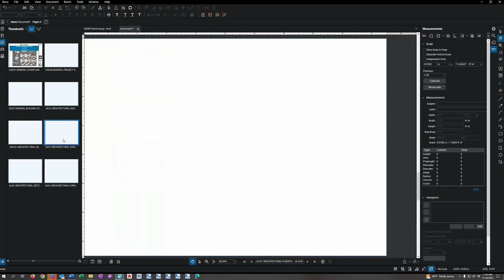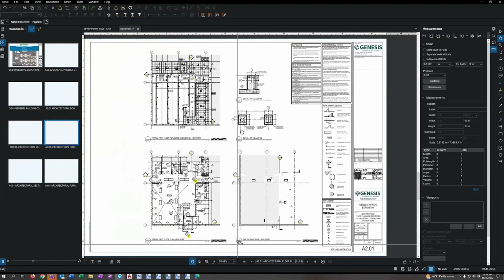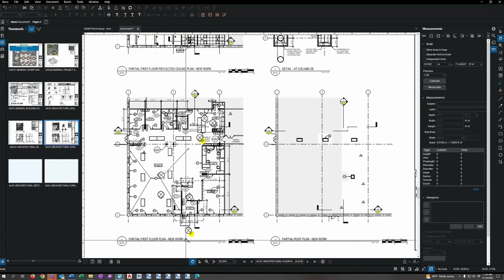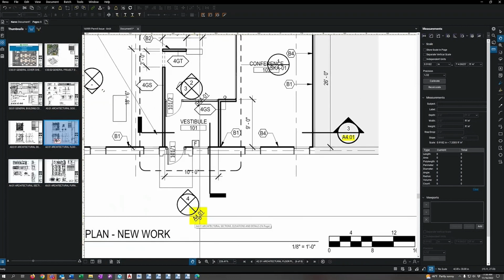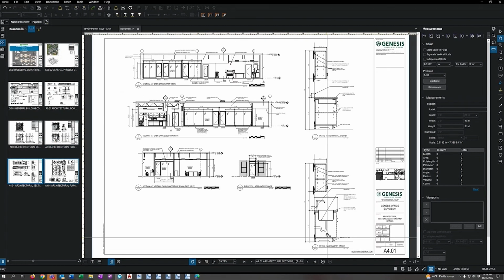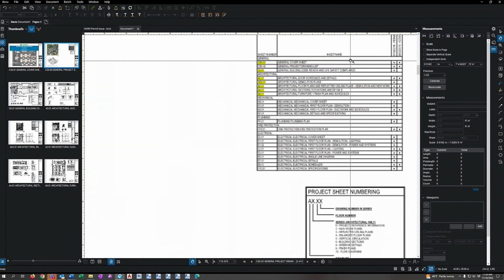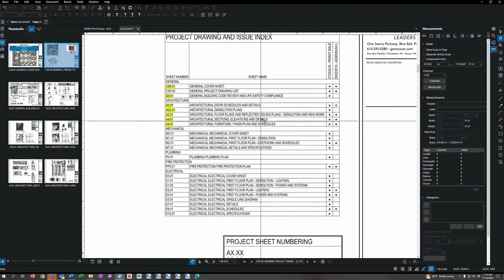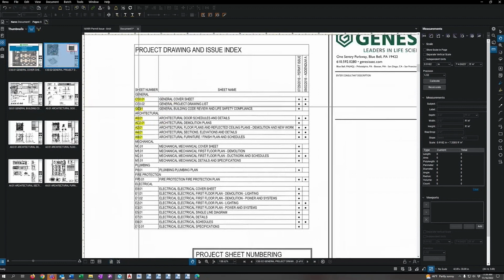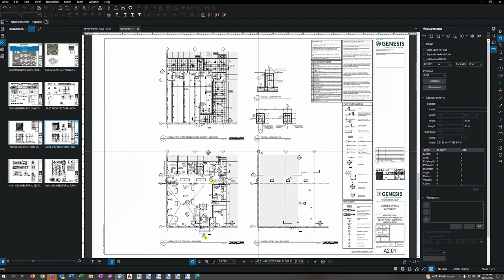if we go to a different page, you can see highlighted in yellow where all the links are. So it found this on the page, and A401 now points to that page, which for us is down here, page 7. So if I click it, it takes me to that page. The beauty of this too is if you have a drawing list page, especially if you don't have your page label set, it'll turn the drawing list into a hyperlinked list. And you can say, oh, I want to see the RCPs. I click and it takes me there.